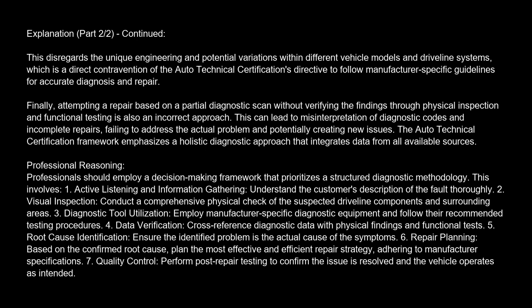2. Visual inspection. Conduct a comprehensive physical check of the suspected driveline components and surrounding areas. 3. Diagnostic tool utilization. Employ manufacturer-specific diagnostic equipment and follow their recommended testing procedures. 4. Data verification. Cross-reference diagnostic data with physical findings and functional tests. 5. Root cause identification. Ensure the identified problem is the actual cause of the symptoms.